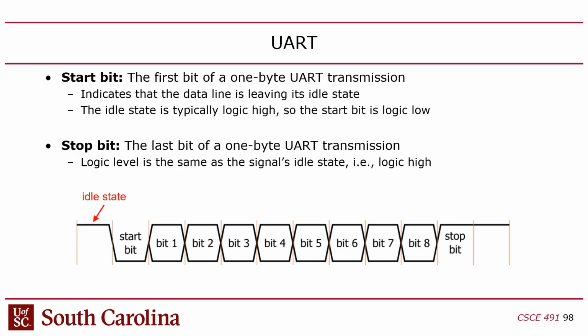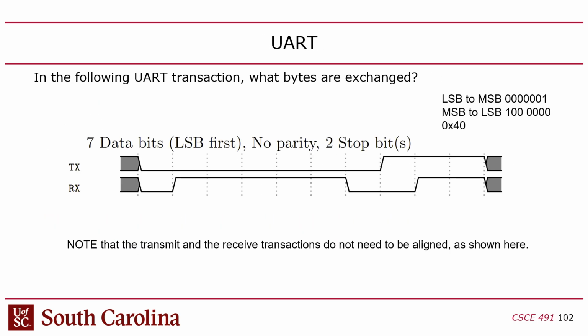So I have some examples here of UART. These are a little bit misleading, though, because I wrote this software that generates these timing diagrams, but it was originally designed for SPI, which means that the transmit and the receive are aligned perfectly. You're doing one transmit and one receive simultaneously, which is not realistic, because usually you're doing a transmit or a receive. You don't necessarily do them both at the same time like you do with SPI. So these timing diagrams are a little bit misleading because they show the transmit and the receive happening at the same time.